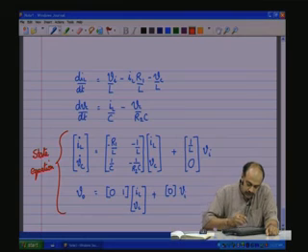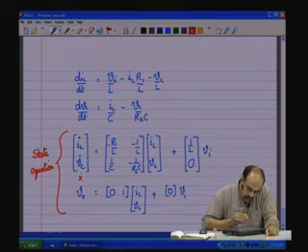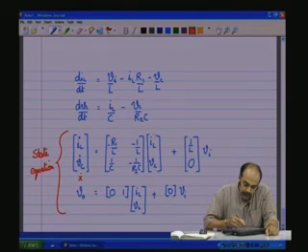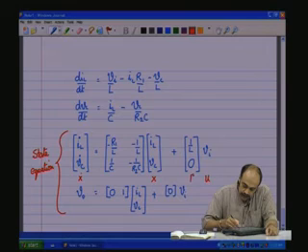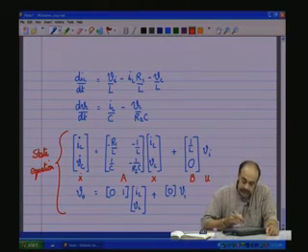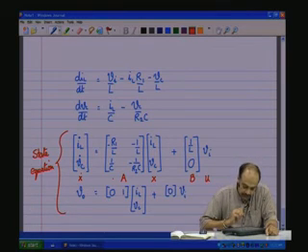You see here, this is the derivative of the state vector x dot, and this is the state vector x, and this is of course the input vector. In this case this is a single element, and therefore, it is a 1 by 1 matrix, and here is the input matrix, and this is the matrix which describes the circuit in terms of the circuit parameters, R's and C's and all those things.